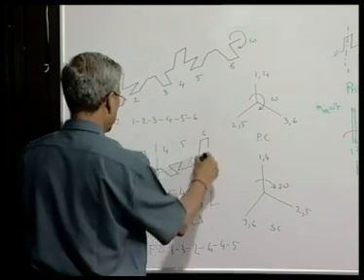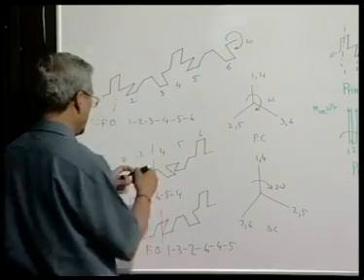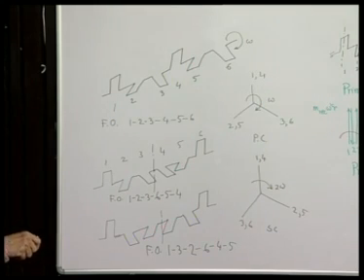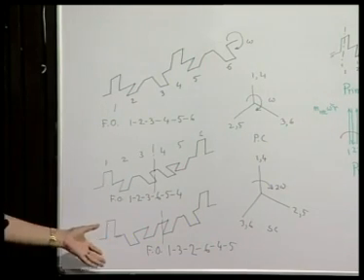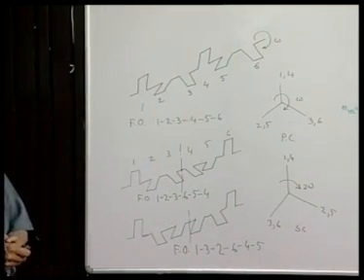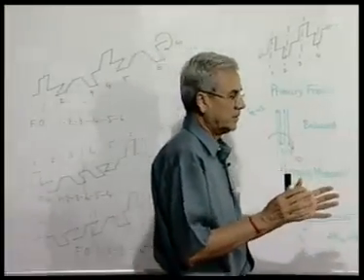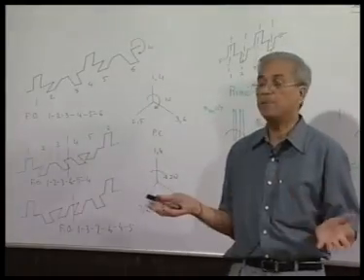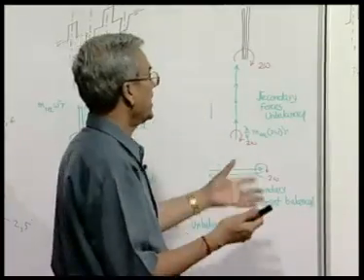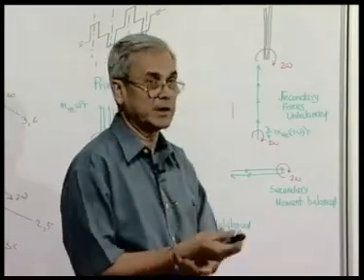You can see this is symmetric about this, this is symmetric about this. So, in all these cases, if we draw the primary force and secondary force, primary moment, secondary moment, it can be easily shown that it will be completely balanced up to the secondary. Thus, the arrangement of the same engine, if properly designed, can be completely balanced without taking the trouble of attaching active measures like putting separate balancing masses. The unbalanced forces themselves will neutralize each other.